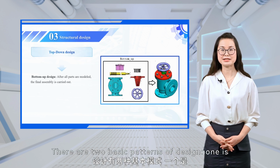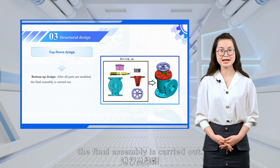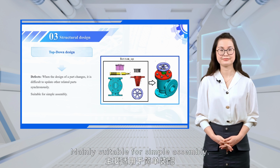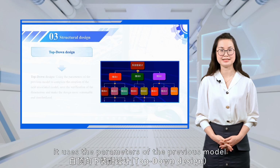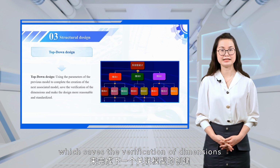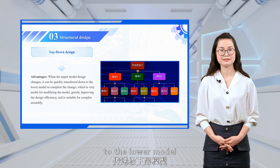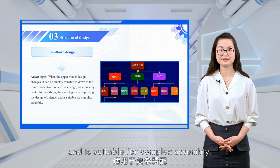There are 2 basic patterns of design. One is bottom-up design. It means that after all parts are finished, the final assembly is carried out. The defect is that when the design of a part changes, it is difficult to update other related parts synchronously, so it is mainly suitable for simple assemblies. Another design pattern is top-down design. It uses the parameters of the previous model to finish the next associated model, which saves the verification of dimensions and makes the design more reasonable and standardized. The advantage is that when the upper model design changes, it can be quickly transferred down to the lower model to complete the change synchronously, which greatly improves the design efficiency and is suitable for complex assemblies.